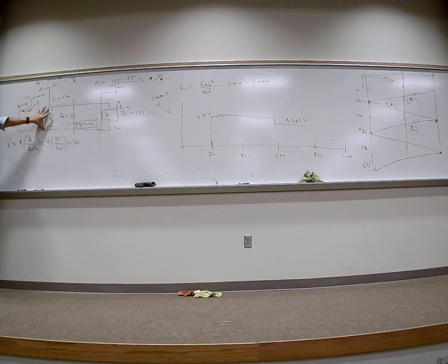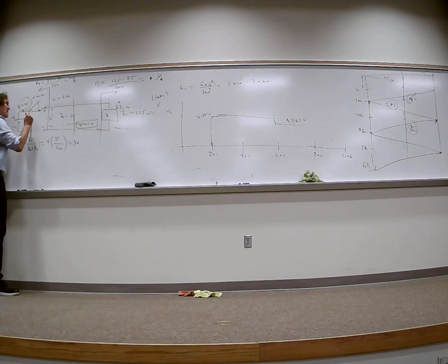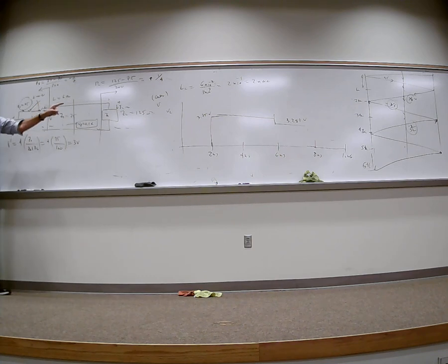Don't use Z0. It's not Z0 any longer. Okay? So if you wanted the current, like if I asked you for the current I at the load versus time, you first need the voltage at the load. So you've got to do the bounce diagram to see what the voltage is. Then to get the current, you take 4 minus that voltage. So you find the voltage across this resistor and divide it by 25. Y'all hear me on that?